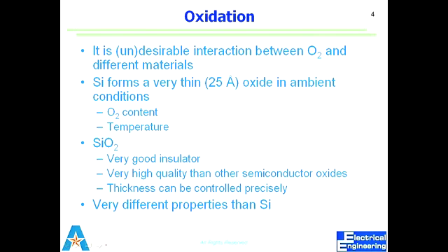If I want to leave that native oxide, because if I'm depositing something, those metals, maybe chrome, may not stick to oxide at all. It would stick to silicon very well. In that case, I might want to get rid of it. But if I just have to oxidize the wafer further, I can leave native oxide there and continue oxidation on top of that. Now, my estimate will be adjusted for that initial oxide thickness, right? So we'll see the relation, how we calculate. We'll have to figure out how to incorporate that oxide which is already there before we start oxidation.